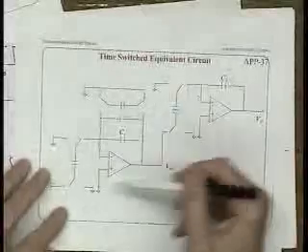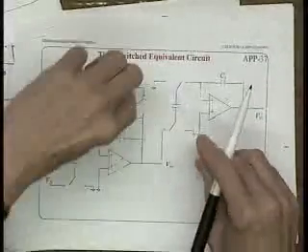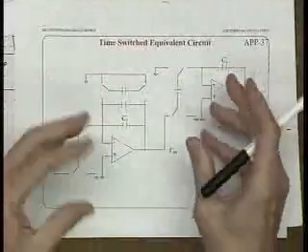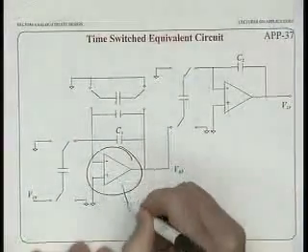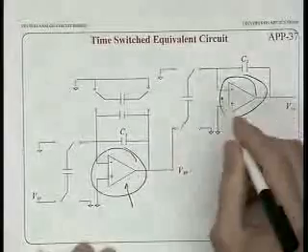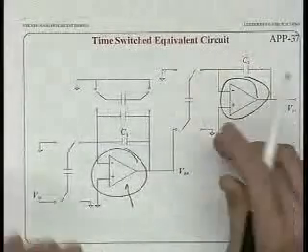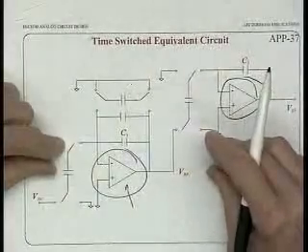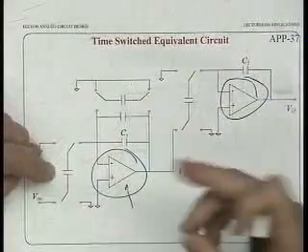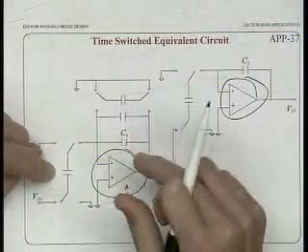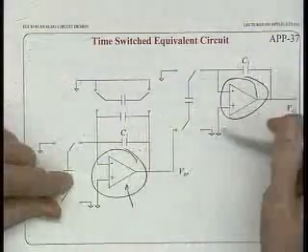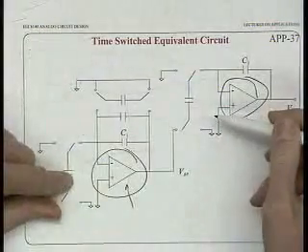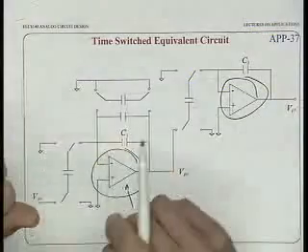So it can look like this. This is a portion of a switched capacitor filter. These are all the switches, and you put them on the bottom plate instead of the top plate and all that kind of stuff. But the core of this circuit is these op-amps, and that's what you've been designing. So basically, you take the op-amps you've done in this course, and you throw around some stuff like this. This only drives pure capacitance. That's much easier to do than driving resistance, right? So that's another big win for this. It's a purely capacitively driven circuit. And you can make really complicated filters, of arbitrary complexity.